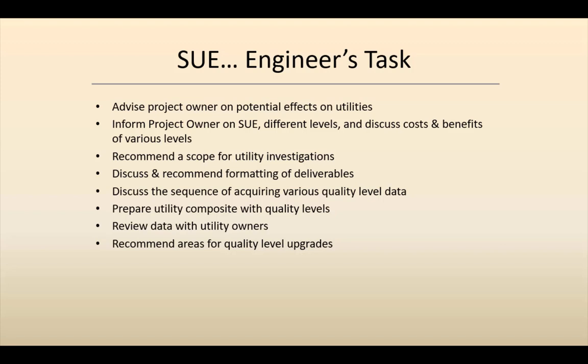For example, in a particular area, if a very critical structure or foundation is coming in an area of 50 meter by 50 meter, the remaining area can be left at quality level B, but at least in this particular area it has to be upgraded to quality level A. So this is the task of the SUE engineer.